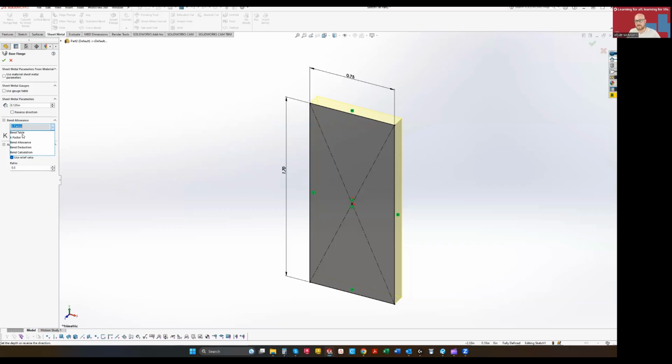When you're bending sheet metal, hypothetically, if you have a 2x2 square of sheet metal and you bend it right in the center, a 90-degree bend right at the 1 inch mark, the formed part is actually going to be more like 0.98 for one flange, and 0.98 for the other flange.